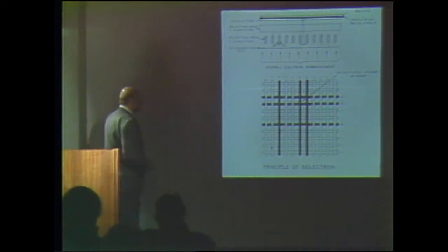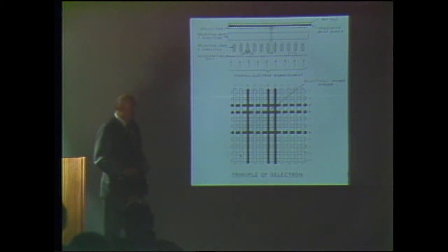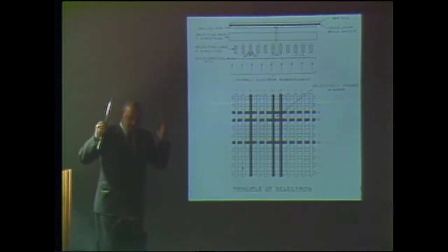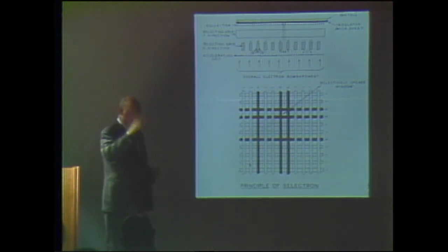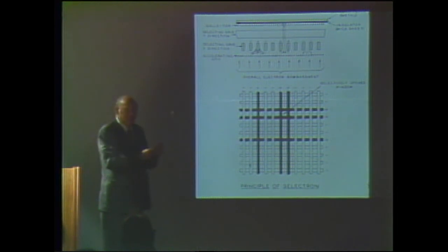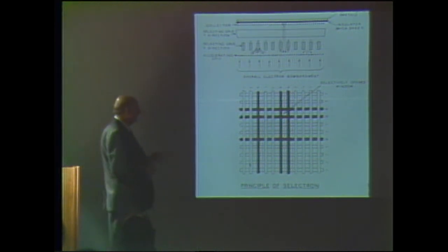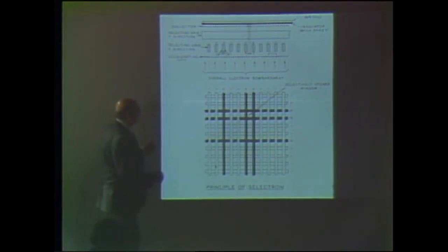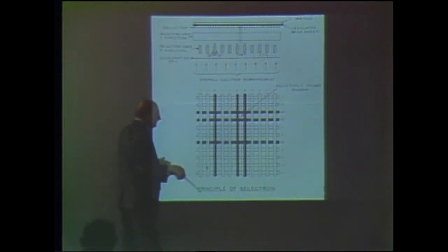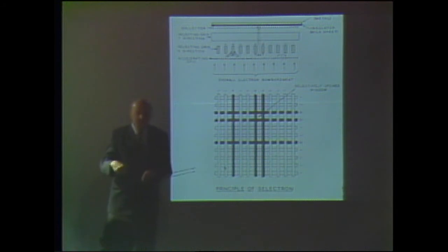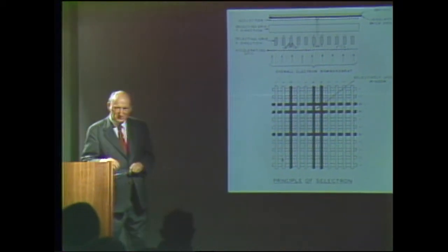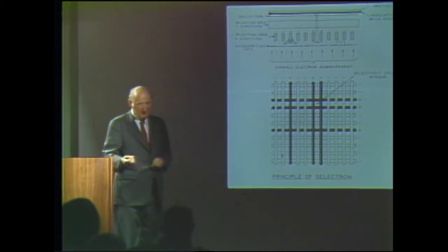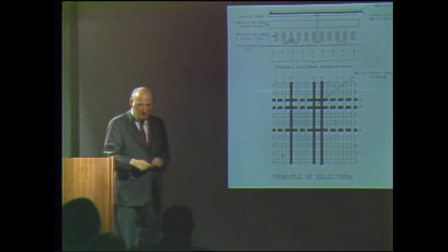Now, the idea of the Selectron is simply that if you are going to be in the digital world, darn it all, build it. Build an XY grid, and then when you open a particular window, the electrons will go there and nowhere else. There is no uncertainty about digital to analog deflection. Well, as Morris pointed out at the beginning, of course, if you make many wires, one way or the other, and you have to put them through the vacuum, through the base, this is a pin problem that existed then, and even more so because you have to go through a vacuum envelope.